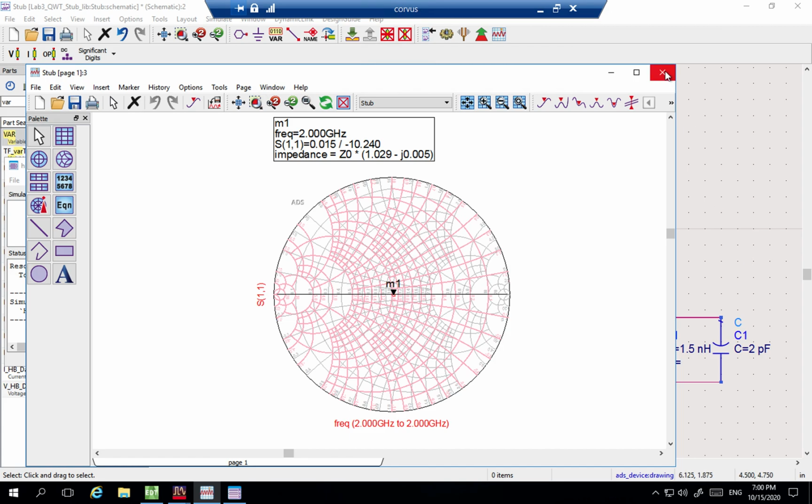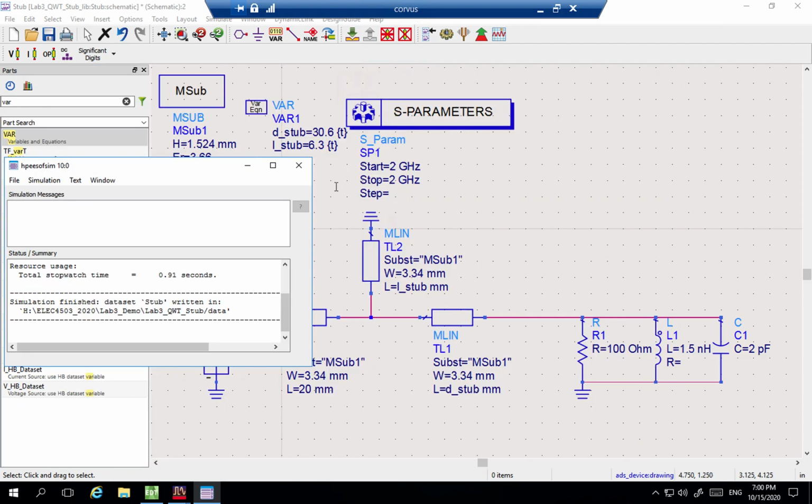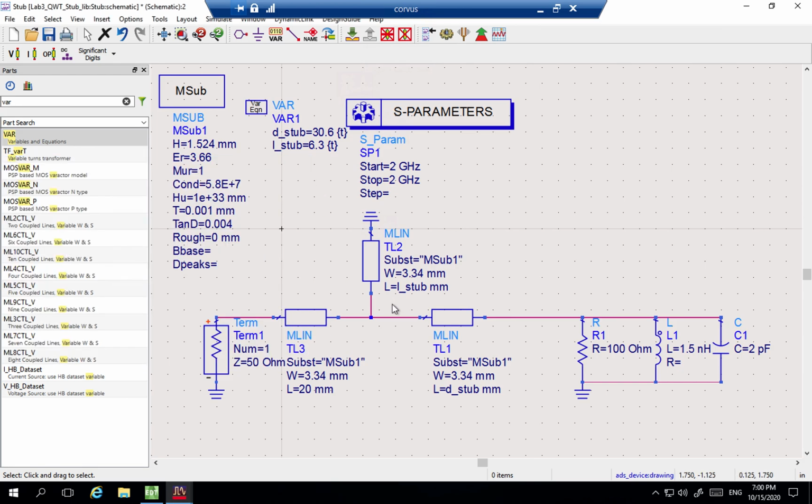Good. So that's what I wanted to show here, because I did use it on HFSS, and I wanted to implement the exact design that you see here. One other thing: once you've designed this, and when you go into the report, I ask you about the Smith charts and intermediate steps. You don't have to redo everything from scratch. What you can do is simply short circuit and open circuit components as you need to.